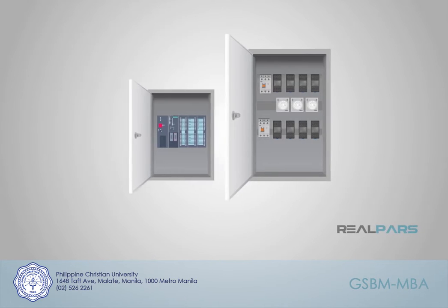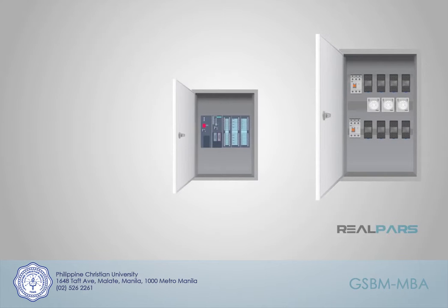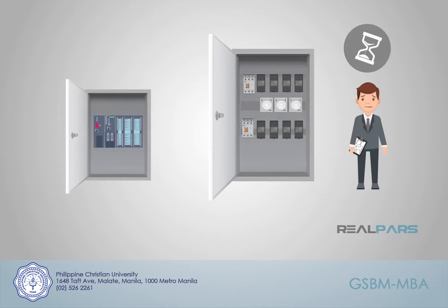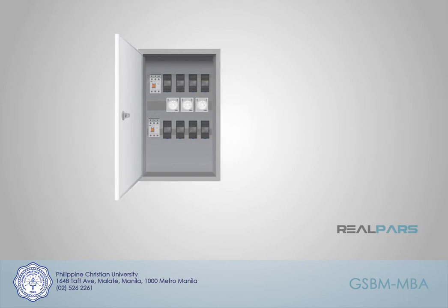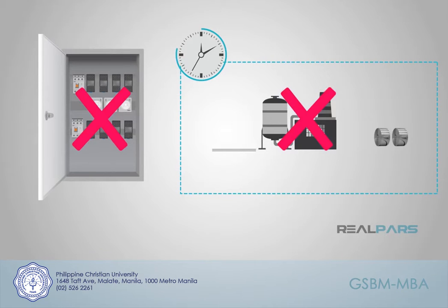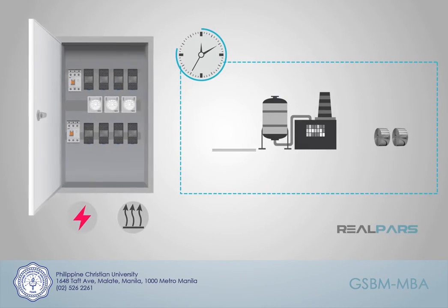Initially, the PLC was a replacement for panels of relays, devices that turn on and off. Making a machine run using relays as logic was time-consuming and challenging, and making a change in the logic or the operation of the machine was almost as complicated as starting over. Relays also fail far more frequently than computer components, so relay logic required more downtime to keep it running than newer PLC-based controls. On top of all of that, relays use a lot of electricity, make lots of heat and soot, and take up lots of space.